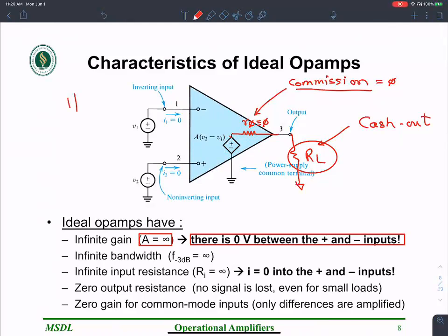Typically what happens is, when you're doing an op-amp, the way you design an op-amp using MOSFETs is using a differential stage, using NMOS transistors. We will look at op-amps in the coming classes. The gate is floating for an op-amp. The current going into the op-amp is really zero.